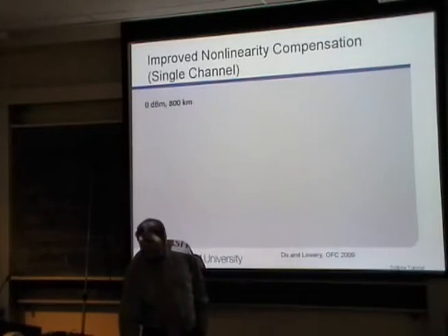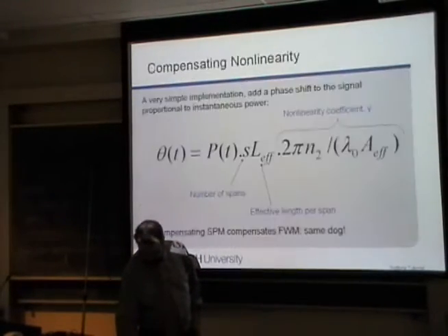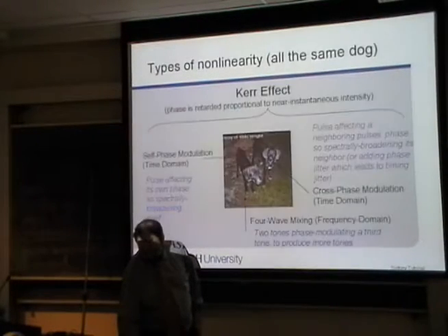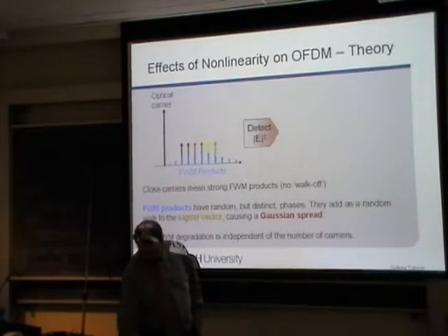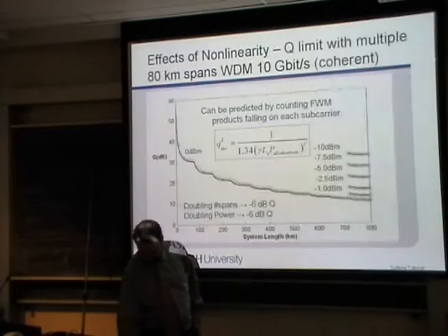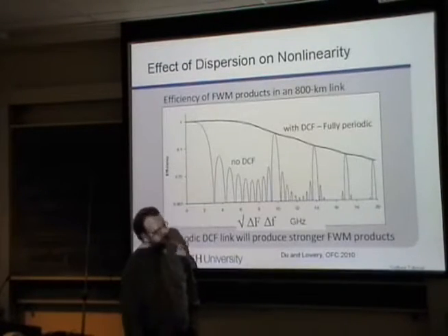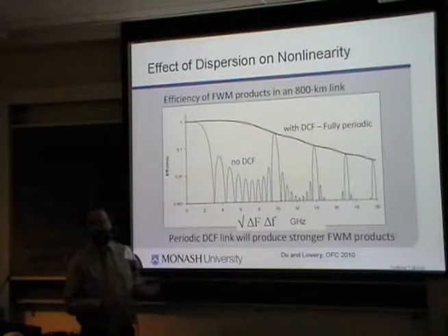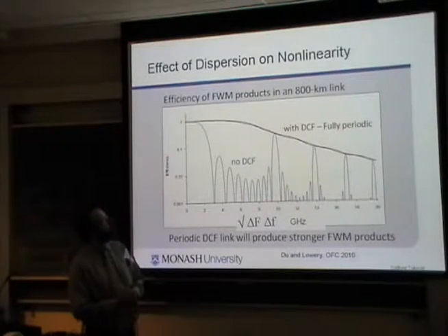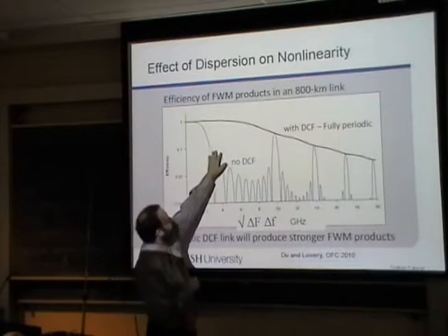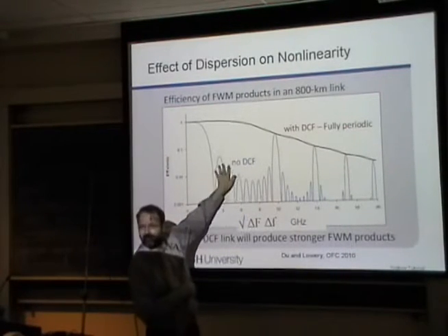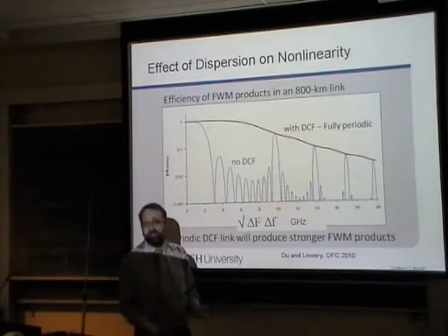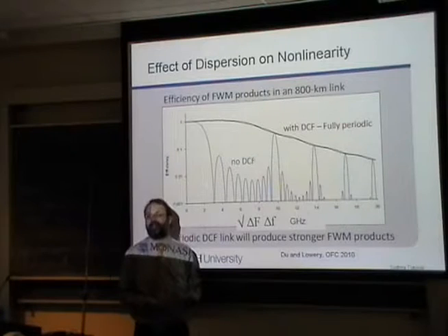And the reason for that, I hope, I've got to go back to this one. The reason for that is this graph. If we have a broadband photodiode and a broadband phase modulator, then it's trying to compensate for these high frequencies. But the high frequencies don't matter because of walk-off. They're cancelled in the actual fiber.